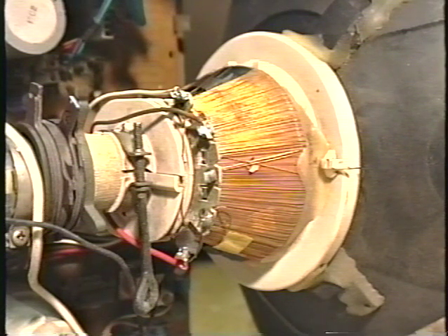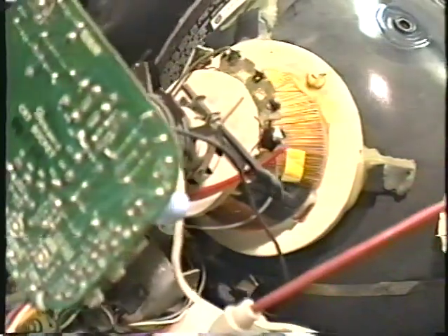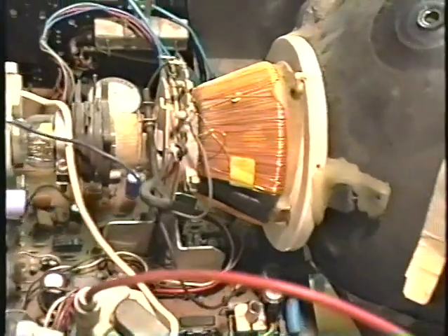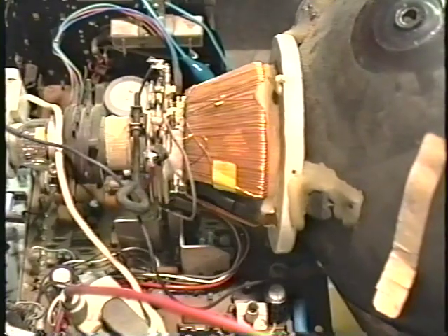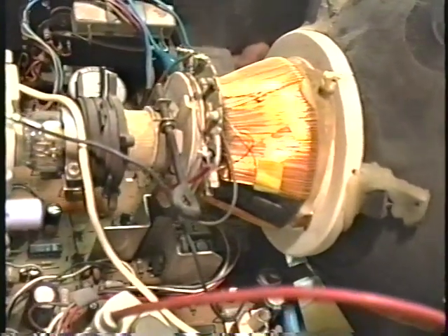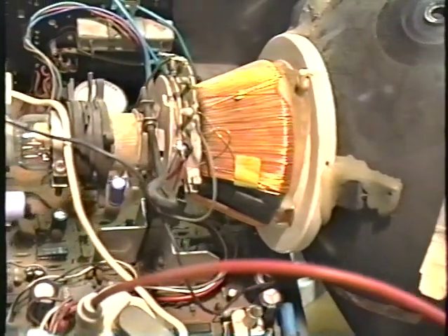Down here on the neck of the picture tube, this guy right here, there's an electromagnet assembly, and it's called the yoke, Y-O-K-E. Now, all I've done here to get this spot on the front of the screen is I have simply disconnected the yoke. I simply unplugged the yoke. There's a connector down here that we'll see later on that I disconnected.